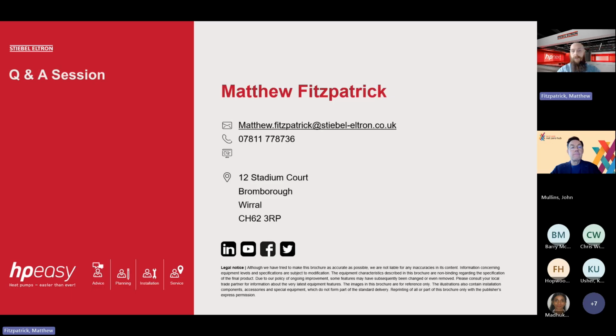And rather than a plate heat exchanger on a wet system, a radiator system or a heating system, they are a bit more difficult to change. So we want to keep any debris, any muck, any build-up away from the heat pump, which is where that plate comes in. But if we have the ability to remove those old cast iron radiators and install new ones, it's the best approach. If we are stuck and must retain what we already have, then we'd integrate that plate heat exchanger.